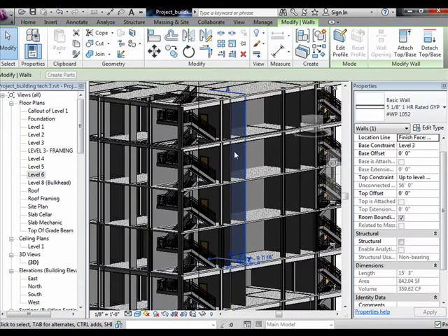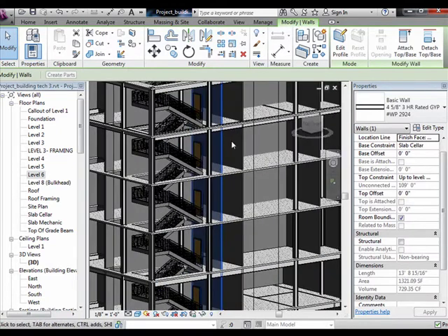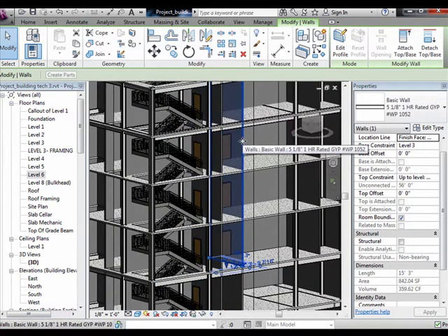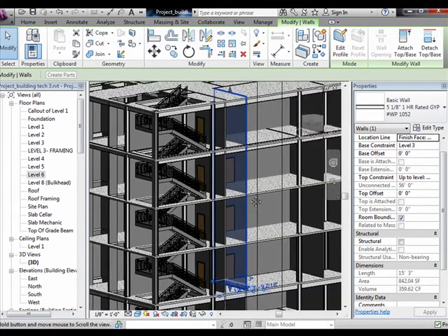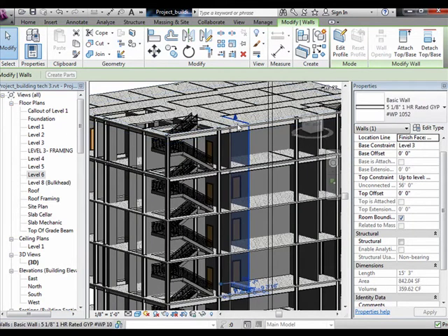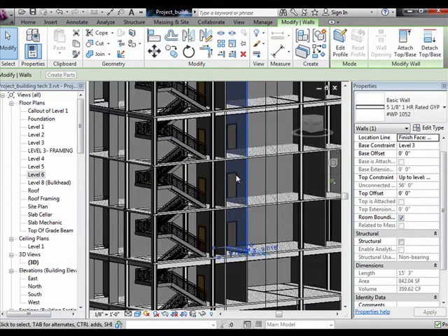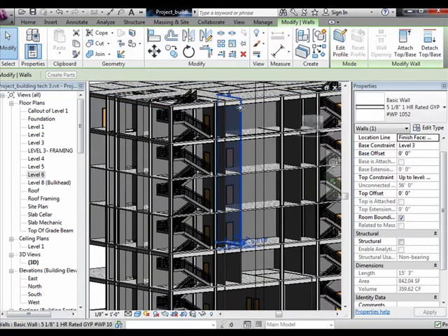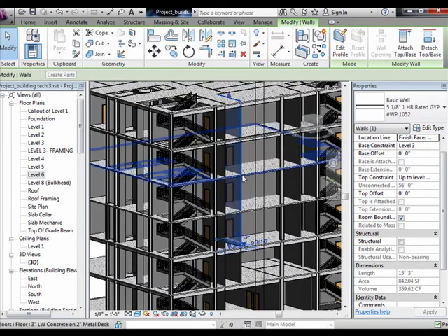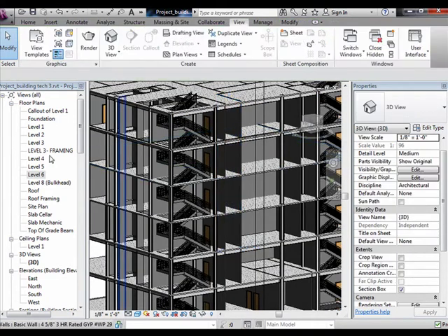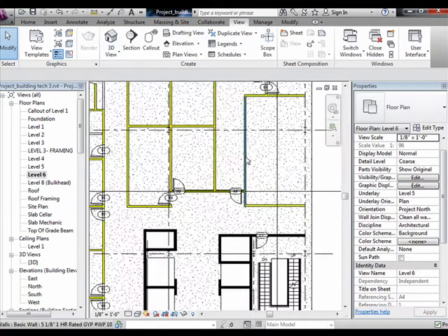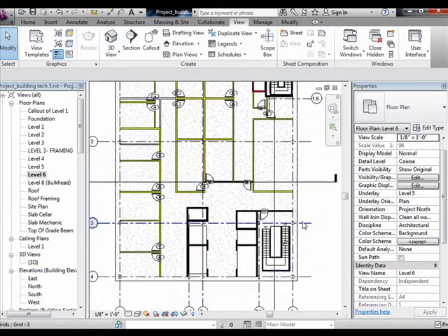Okay, so as a rule of thumb, you probably never want to do that. I know it's fine if you've done it already, but I think in general you probably want to keep all your partitions and all your components built floor by floor, other than stairs and shafts, and some other vertical components. But like partitions, a carpenter wouldn't come here and install 50-foot framing, right, for a wall. It's just not possible. So that's why the view range is not working. But I'm going to skip that step and go right into the framing.